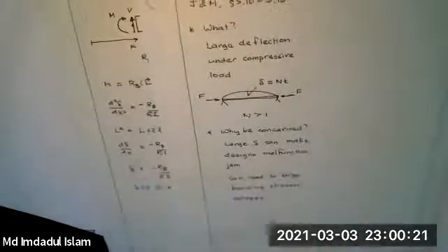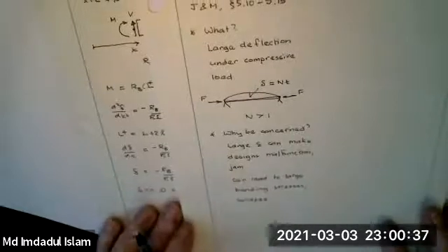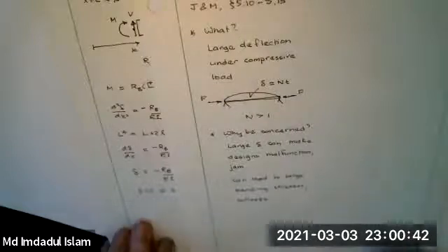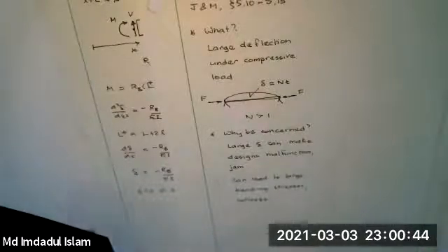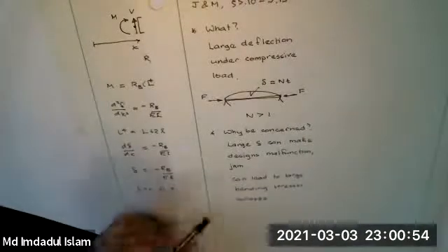If you want to do a demo of this, get a Coke can, empty it, and step on it very, very carefully. That's a very thin aluminum structure. If you step on it very carefully, it'll take your weight. I'm not sure it'll take everybody's weight in this class, but certainly I've done it and it'll take my weight, and it's about 180 pounds. If you then reach down and touch the sides and promote buckling, they'll start to buckle, the thing will collapse and the can will be crushed. Okay, that's a simple demonstration of this sort of phenomenon.